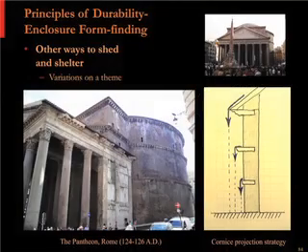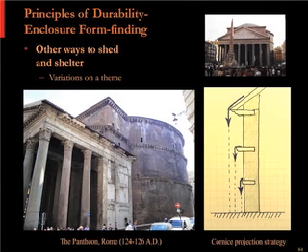And this building at the right, which I found really interesting, they're doing it in both. So you see these huge wood beams very closely spaced, but then where they have, I imagine, a demising wall, then they have these huge stone corbels as well, 4 of them across the facade, stepping out that facade. And also you see the projection of the window hoods, the window sills, all those elements to shed water, particularly in a place like Venice, which is right on the ocean, obviously, and it's going to get a lot of wind-driven rain.